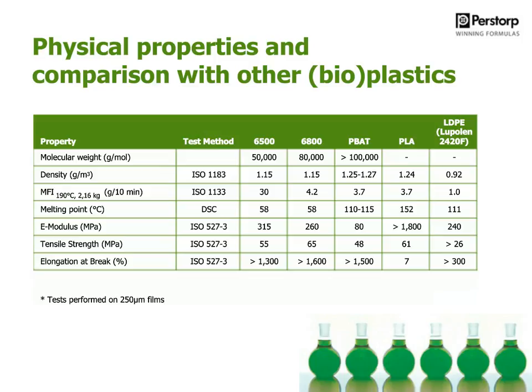The properties of polycaprolactone are very much molecular weight dependent. So the higher the molecular weight, this will have an influence on the E modulus. As you can see, you will have a softer product, and you will have a modified tensile strength, as well as the elongation at break. Not a big difference, but it will be noticeable depending on how much you're introducing in your formulation.